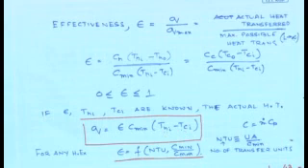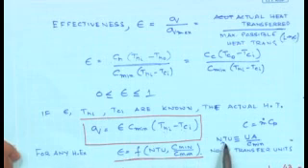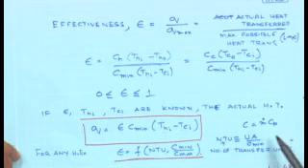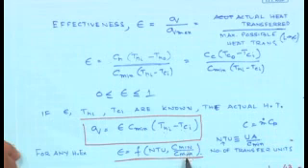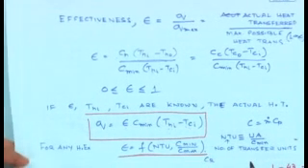So the entire exercise that we are going to undertake in this part of the course is to find a relation for epsilon, and for any heat exchanger epsilon is going to be a function of NTU, where NTU is defined as the number of transfer units. It's UA by C minimum, and the ratio of C minimum by C max, which is sometimes also referred to as CR. The ratio is expressed as CR.